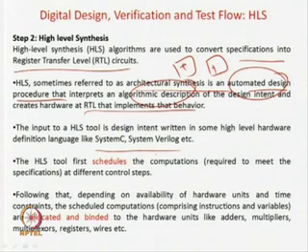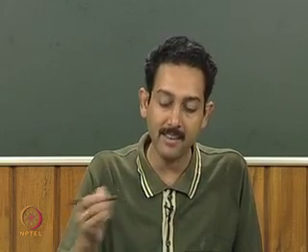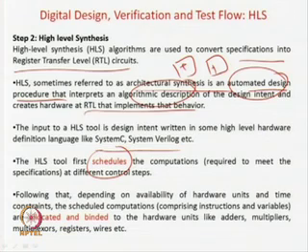So, it is very easy to write hardware specifications in this. What this high level synthesis tool will do is finally generate an RTL design, or an architectural block diagram. First, it will have to schedule the computations at different steps. We will see what we mean by scheduling.